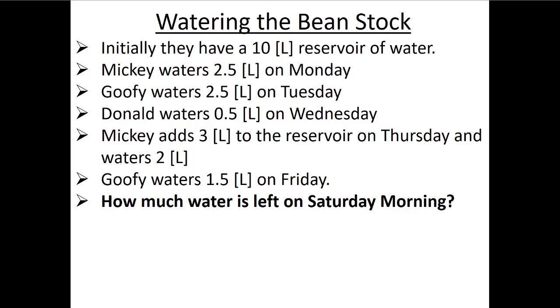But here, liters and kilograms are 2 different things, right? So to get the mass, we'd have to multiply by the density, or divide by the specific volume, because this is thermodynamics class. But if we make the assumption that the density or the specific volume are constant, then our conservation of mass equation is going to look like conservation of volume. But we have to remember, conservation of volume is not a thing by itself. It's really mass that's conserved. And we'll see that better in the next problem.